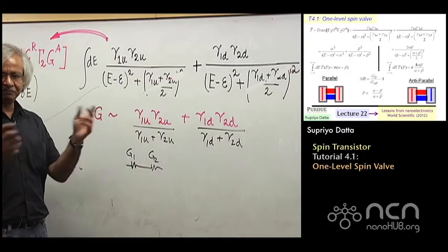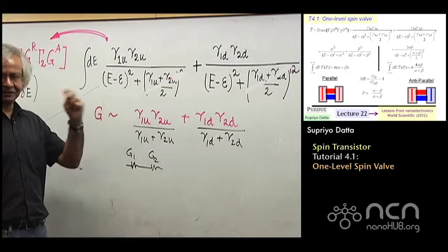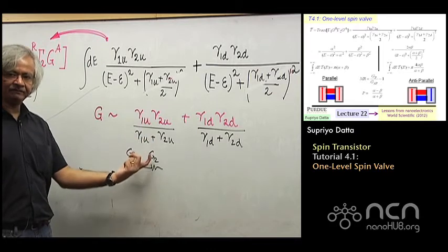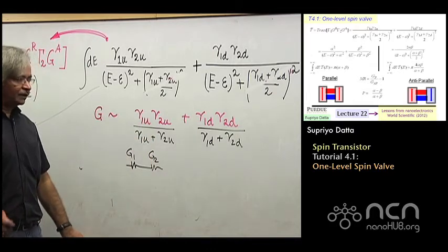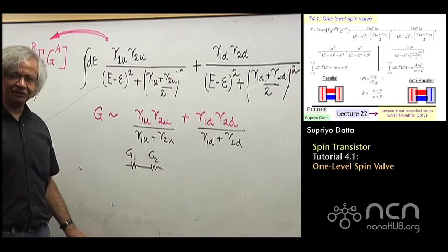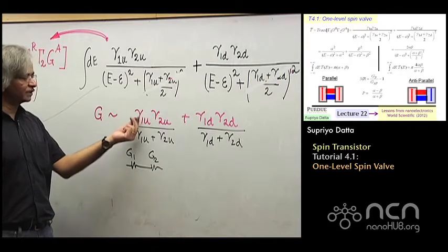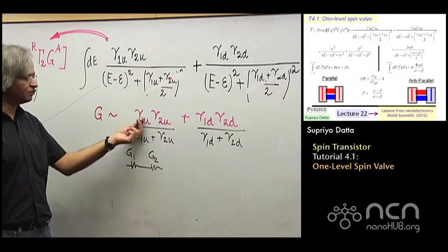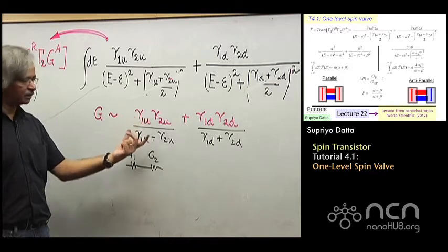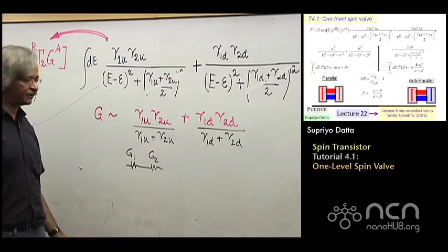So if you had a simple resistor model with a conductance at the two ends, that's what you'd have got. But what we had for the tunneling resistor was kind of different. The net conductance was like the product of the two, G1 times G2, not G1 G2 over G1 plus G2.